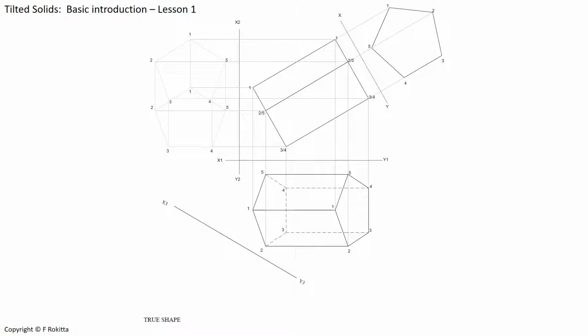Once all of the corners of our prism are carried over onto our side view, we can now draw in all the lines that connect those corners to one another, and this will create the profile of the ghost view for our right view. Once we have done the ghost view, or the profile for the right view, we can determine which parts of our side view will be solid and which parts will be hidden.